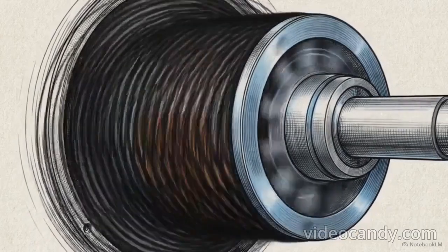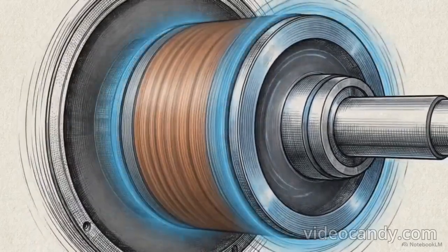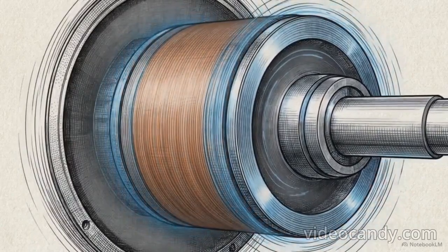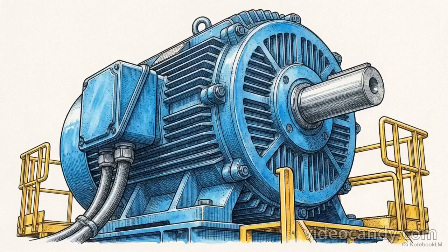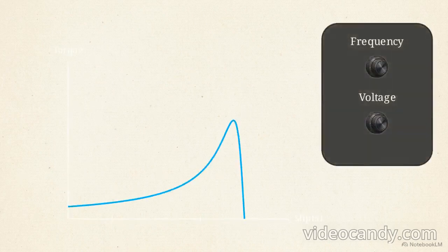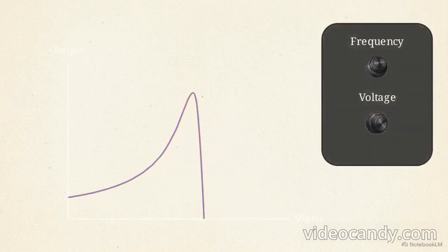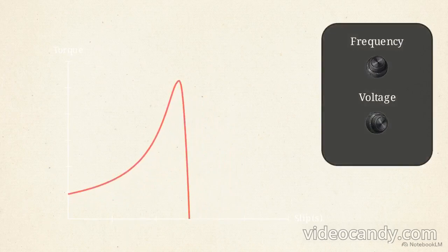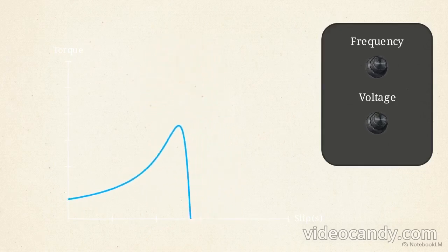The outputs of these three massive converter blocks are then wired directly into standard Y or delta motor configurations. This synchronized array outputs three distinct, heavily filtered voltage phases, precisely separated by 120 electrical degrees. By accurately spacing these synthesized output phases, the network generates the smooth, rotating magnetic fields required for high-torque industrial traction. With the switching topology solved, we reach the ultimate engineering goal, precisely controlling the speed of massive AC induction machines.